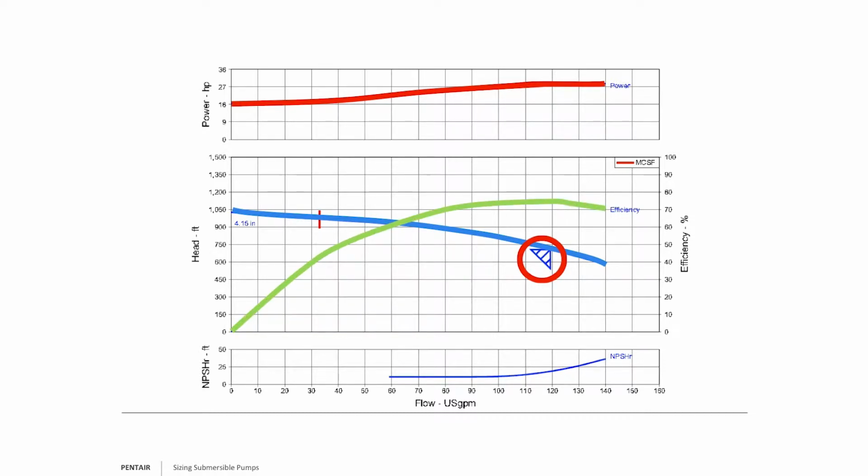The green line you now see is your efficiency curve. And if you look at the best efficiency point, you can see that the efficiency curve is skewed to the right. That's why I caution people, don't assume it's always going to be dead center to the curve. That's your minimal, constant, sustainable flow. That means if you're operating less than that, you're going to have issues with the pump. It could be upthrust, cavitation, other issues. So do be cautious.